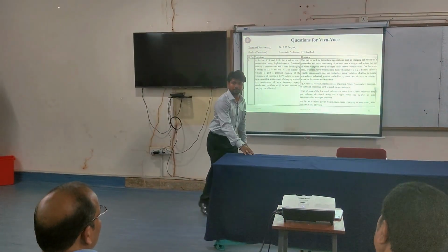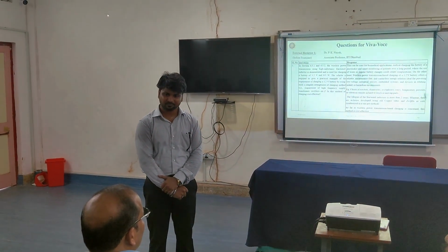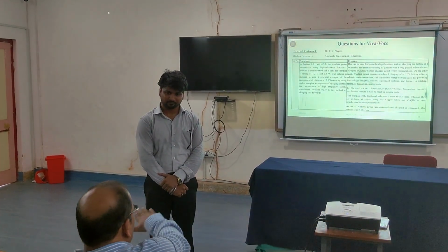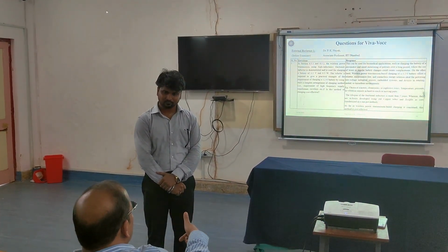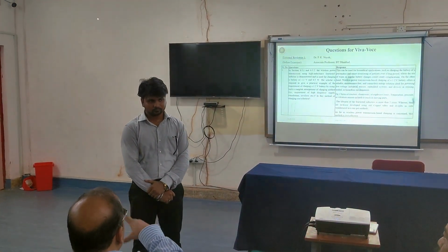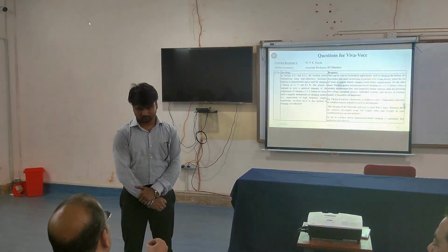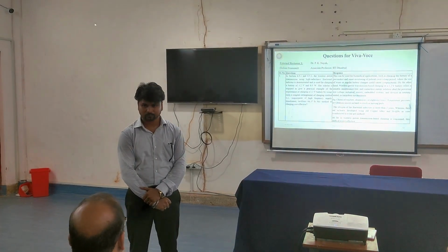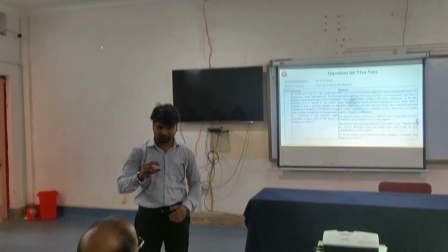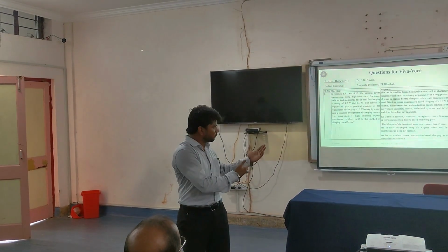But coupling at that distance to transfer this much power is very difficult, I think. Because you see the large surface with small distance, they are making so many arrangements with magnetic resonance. From magnetic resonance, they transmit power from transmitter to receiver. Suppose an AC voltage is there, they make it DC, then DC to high frequency AC. Then with resonance, power transmission is done at high frequency, for high power applications.